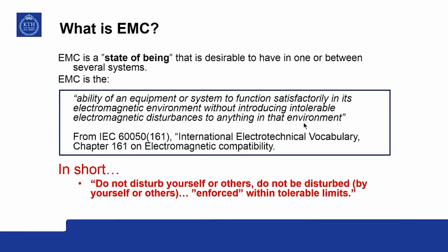And you have to think that you can have two perfectly harmoniously working systems, say system A and system B. In system B, at a later time you make some changes and introduce new electronics or something like that. Then suddenly you might find that system B is now susceptible to system A, because the design of the system has changed and the previously existing electric and magnetic fields or currents and voltages are now becoming disturbing for system B.